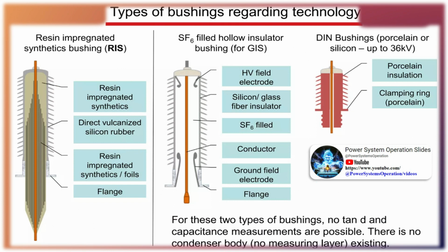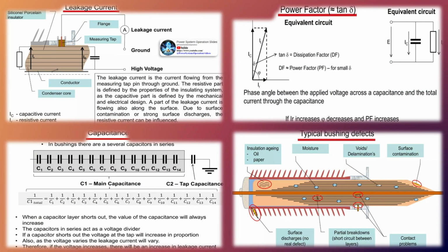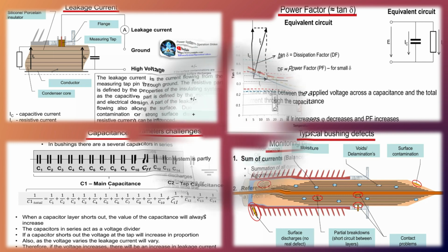Sensor types. Resistive style sensors utilize resistors connected between the bushing tap and ground as the primary method to limit the voltage from the test tap. Should the resistors fail, metal oxide varistors (MOVs) or similar over-voltage protective devices limit the voltage output from the tap to acceptable levels. Current limiting resistors in series with the MOVs can help to prevent MOV failures. Since the test tap of the bushing is solidly grounded through resistors, this type of sensor closely matches the original bushing design where the C2 capacitance is grounded when in service through the tap cover.